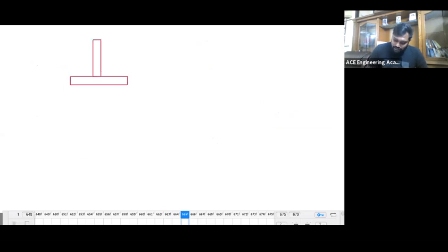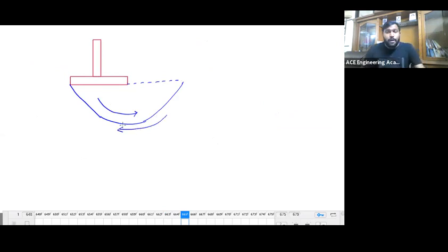Terzaghi has given, right? How has the Terzaghi failure been? In the case of Terzaghi, the failure has an elastic zone, a radial shear zone, and then a passive zone. Yes or no? So this is nothing but the failure and there is a resistance. So by taking these only, these are the moments over here.